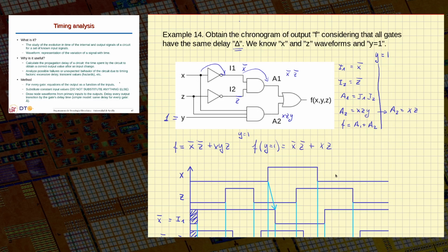Okay. So we see that f is equal to 1 whenever x and z are both 1, or when they are both 0. Okay, actually, you may remember, this is the XNOR operation. This is x XNOR z, right? Which is equal to the exclusive OR complemented, okay?